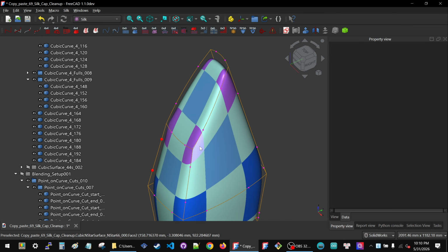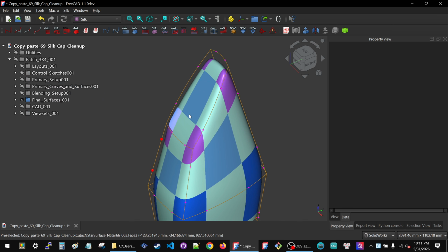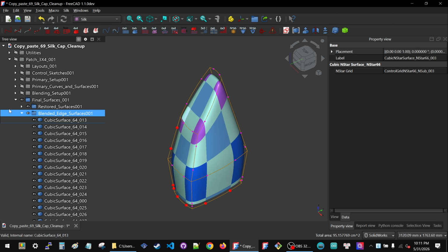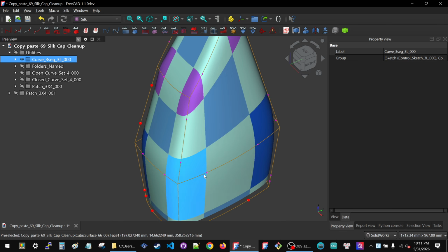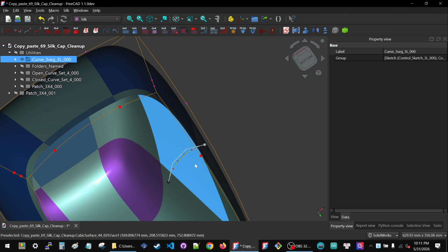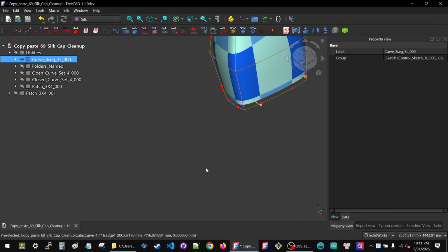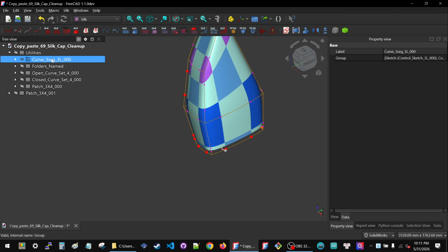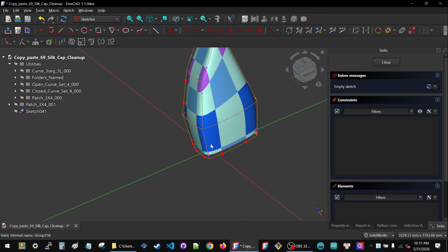Okay, so let's get right to it. To make three-dimensional curves, we can't just draw a single sketch in a plane, right? We still need to have a control polygon that has three lines, but we're going to make it differently. Instead of a single sketch, we're going to make it out of two independent sketches. How does that work? Let's make a sketch. XY plane.